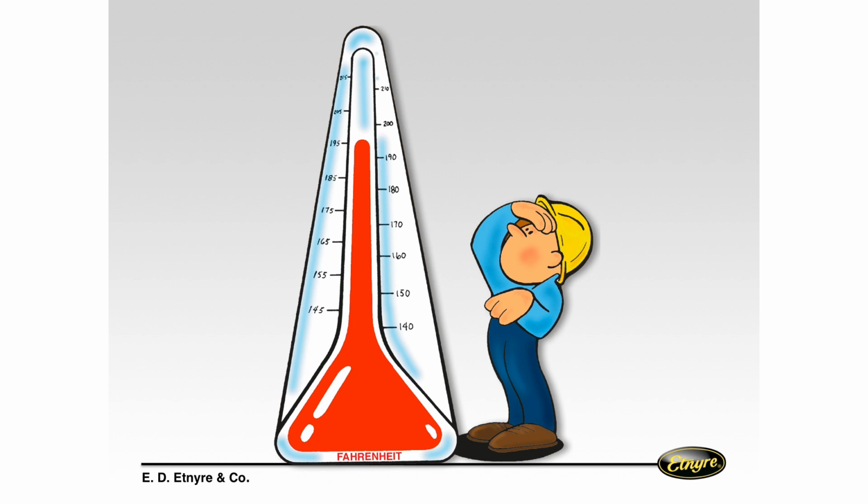Emulsions, because they have water in, we don't want to boil them, because then the water leaves and we're left with the asphalt in our tank, and that's a big mess. We also don't want them to freeze. Okay? If they freeze, they'll do the same thing. Mother Nature will win that battle and she'll pull that oil back apart.